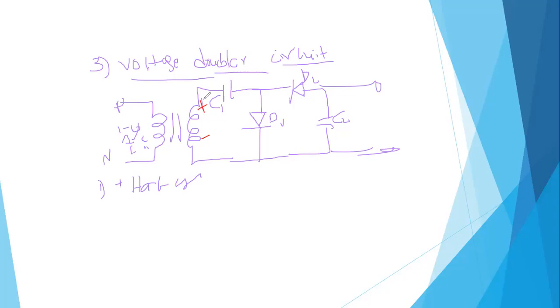During this, the capacitor C1 charges, and the peak value of the input voltage will be taken. So the capacitor charges up to V maximum. Then D1 will be forward biased only. So this is the direction of the current, that is, D1 will be forward biased.